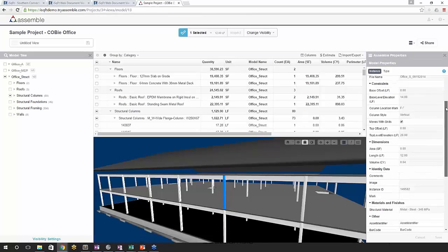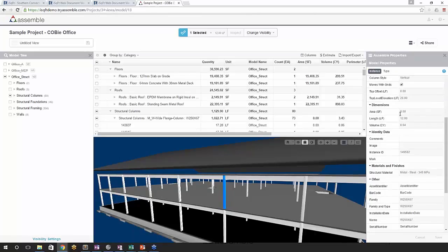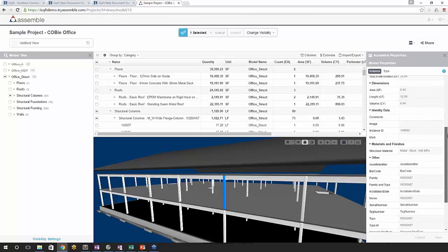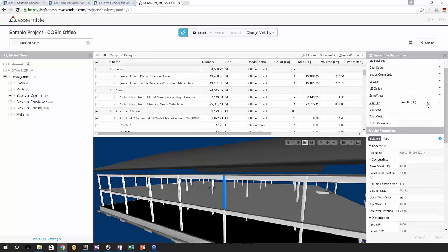If I look at this, I have the square foot, which a beam doesn't necessarily have. So we have the length, the volume, and then we also actually calculate the tonnage by weight by length or weight by volume. And so if you have any of those within a structural component, you have several different things that would be calculated depending on the member type. And so we can grab tonnage either way. But as you can see, I have a kind of primary takeoff quantity. That's this summary right here. And I can actually change or select which one I want to use.